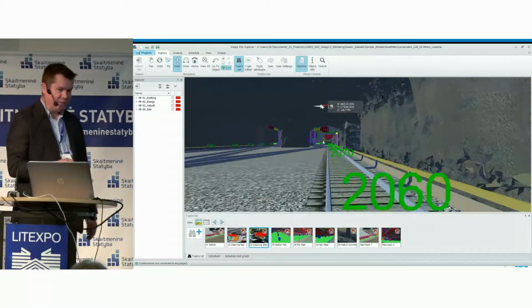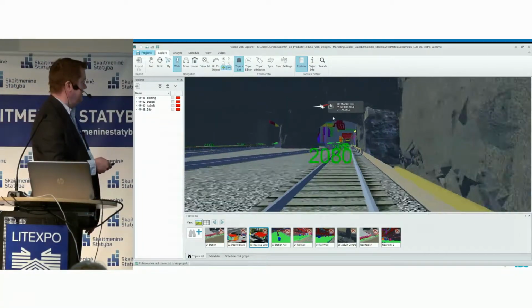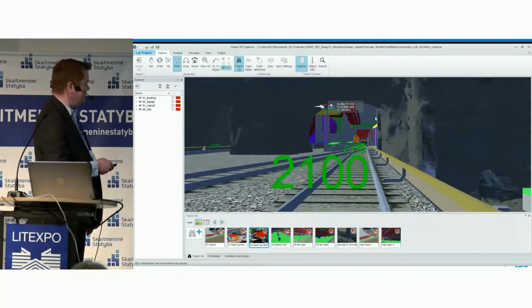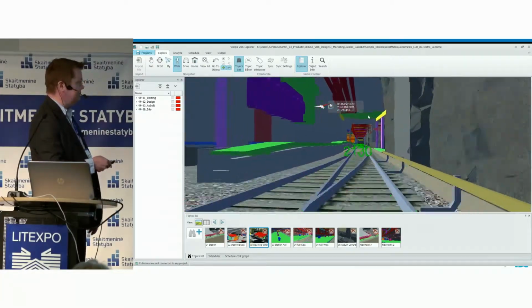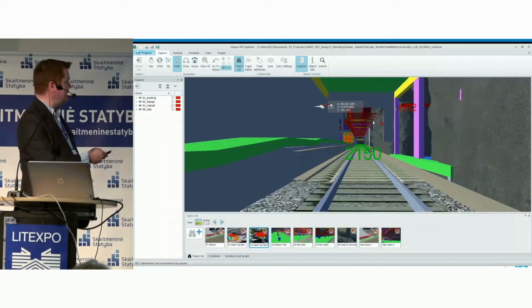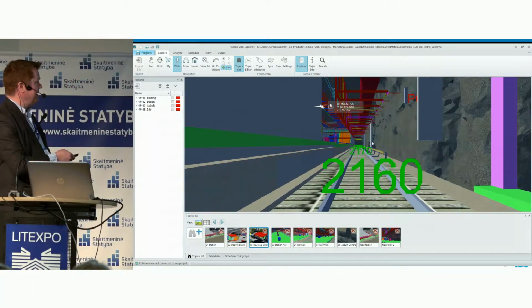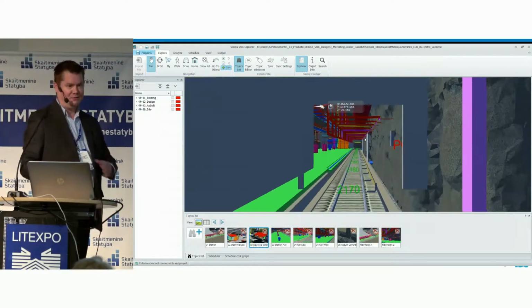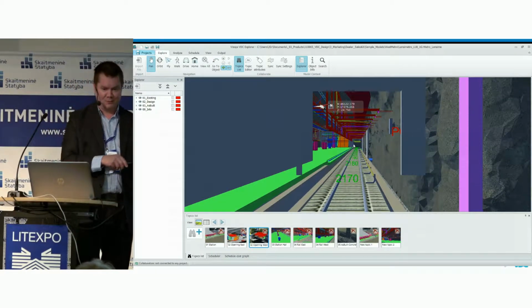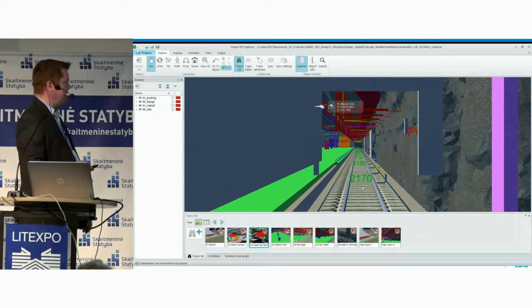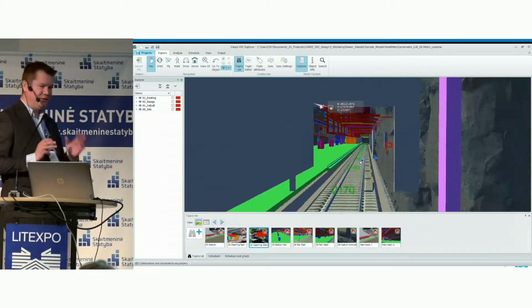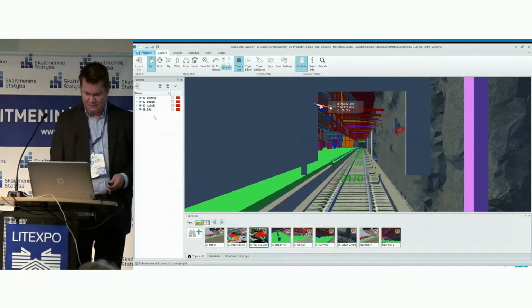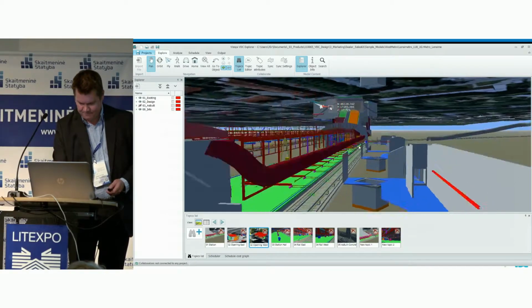And it's very expensive if they don't fit, because the rock is very hard here, and the contractor changes, and the new contractor comes and builds this element, and they don't have the capability of fixing the rock. So then you need to invite the rock blasting contractor back, and that's very expensive. So you need to check all of these before you go to construction.